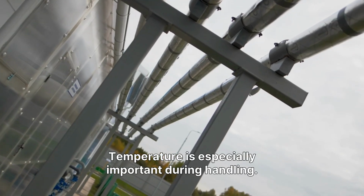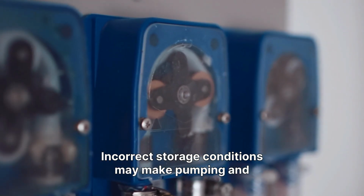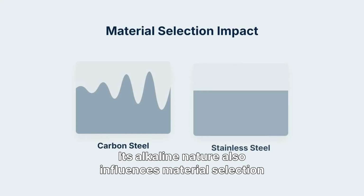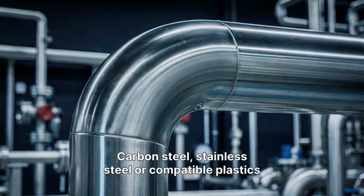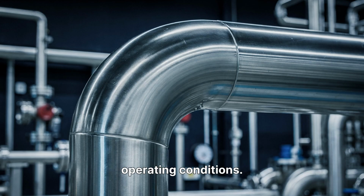Temperature is especially important during handling. Sodium silicate viscosity can increase significantly as temperature falls. Incorrect storage conditions may make pumping and accurate dosing difficult. Its alkaline nature also influences material selection for tanks, pumps, seals, and pipelines. Carbon steel, stainless steel, or compatible plastics are generally selected according to concentration and operating conditions.